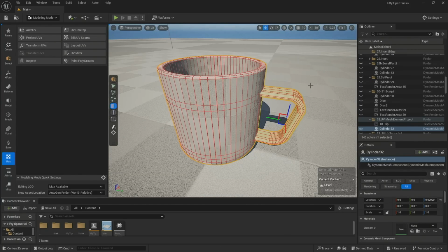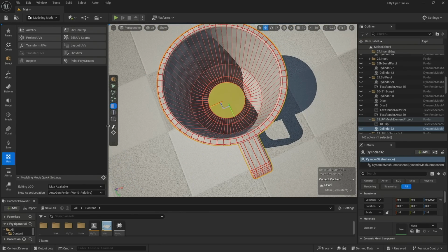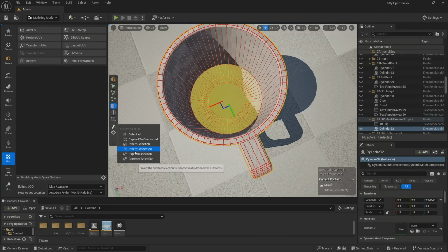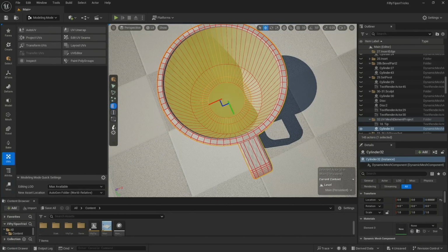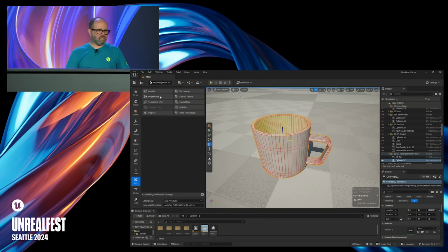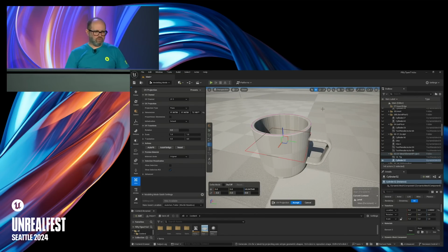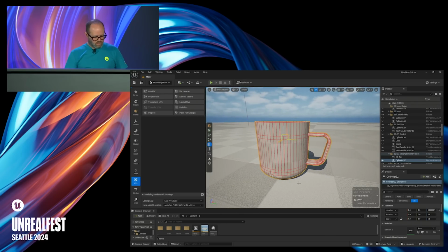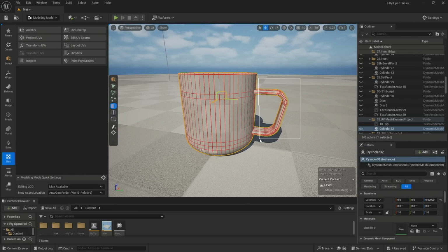So let's go ahead and do that selection, because we're going to go to the UV editor here in a second. Same thing here. Let's expand this guy out. You know, I should have set my hotkeys, which I didn't. Sorry, folks. You gotta watch me do this 5 times. So let's expand this up just a little bit more. So you can do those. Once again, I could say project UVs. I'm just gonna do a planar. We'll do something cool with it later. So we got that. And so those are already selected.